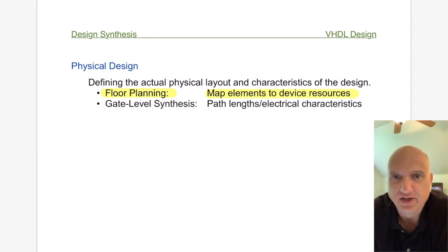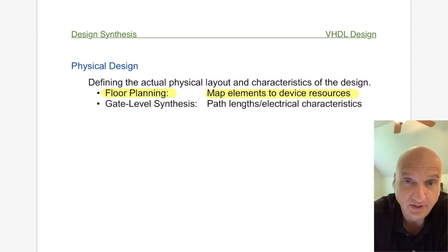So every vendor has its own synthesis tool. Xilinx, for instance, uses Vivado, and that tool basically understands all the hardware that they have in their catalog, and then they know how to map it to those specific elements in that particular hardware. If you're using an Artix-7 FPGA, it understands how the cells are built inside the Artix-7, what the flip-flop resources are, what your lookup tables are. All of that's already pre-known by the developers, so they know how to map that to physical hardware, which we'll learn about a little bit later. So don't worry if you don't know those terms. That's something that's coming up down the road.